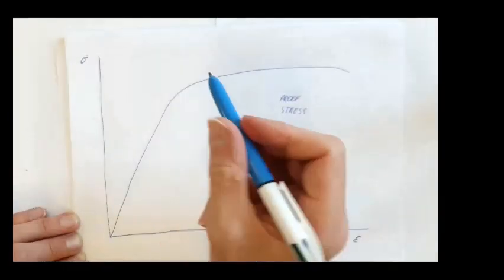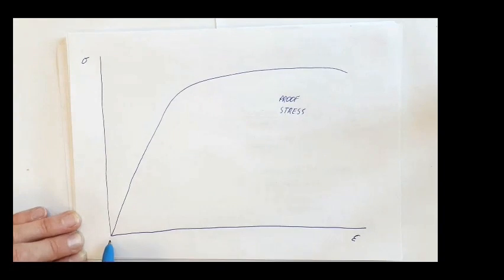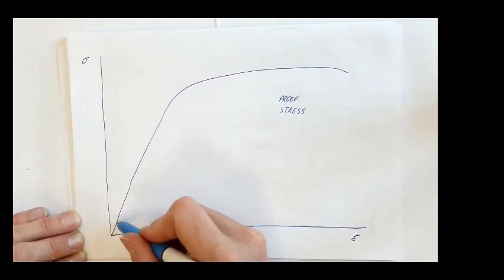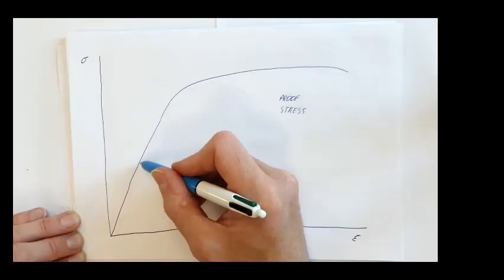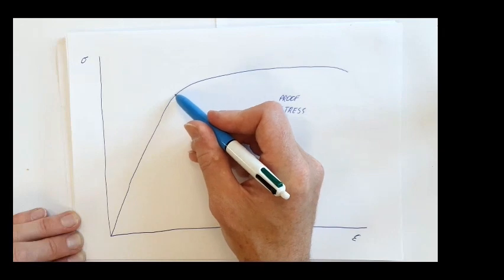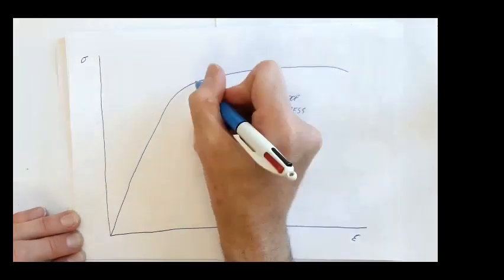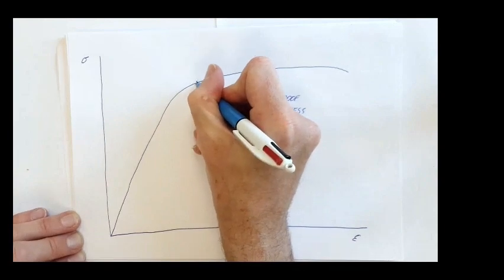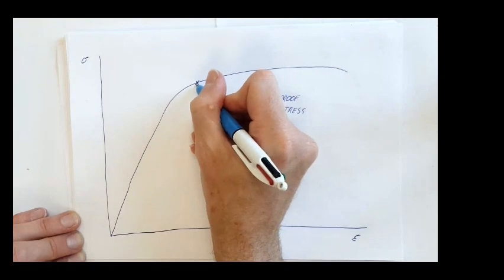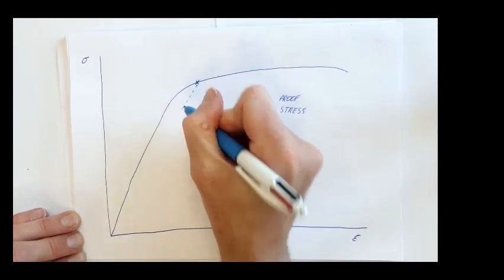And that is the stress at which point, if the load is removed, we see a certain amount of permanent deformation. So we're loading our specimen, we're going up this elastic region here, we start to see plastic deformation. And then let's say we got to this point here and we removed our load, our part would move down this line here.